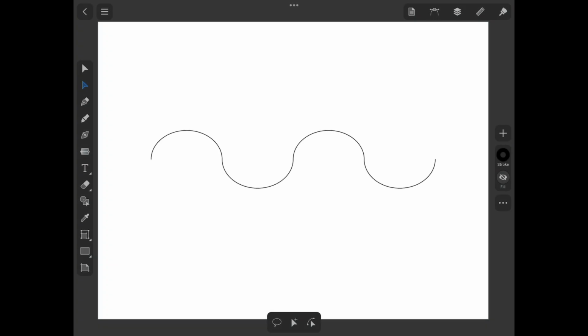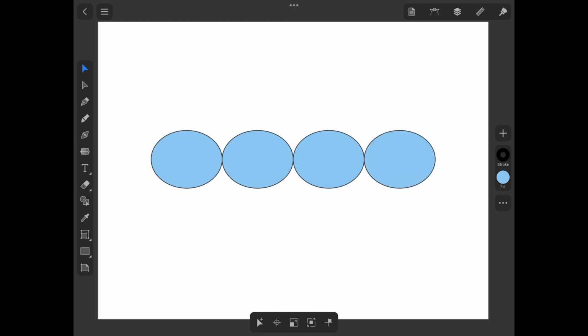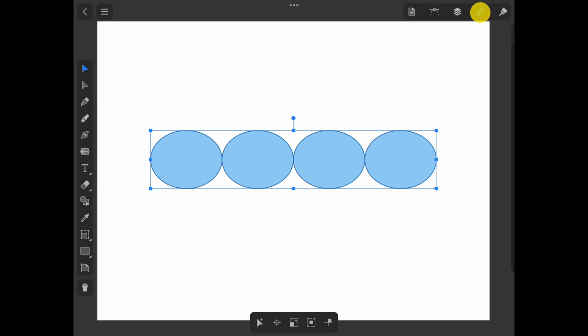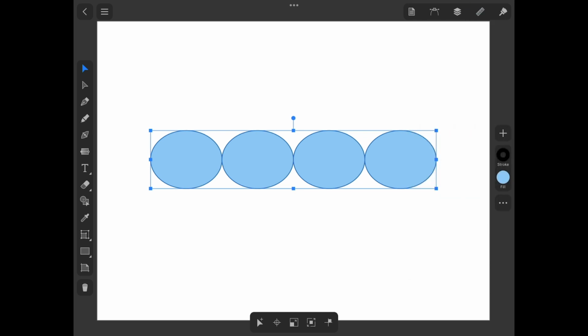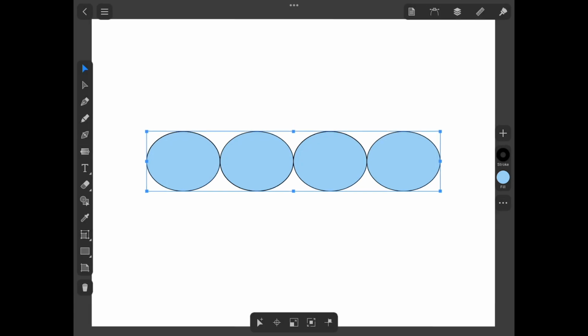Since semi-waves look like halves of ovals, we will use ovals as building blocks. 4 of them will be enough. The ovals must be aligned vertically and snapped horizontally one to another so they touch only at one point. The Fusion tool requires the paths to be perfectly aligned.